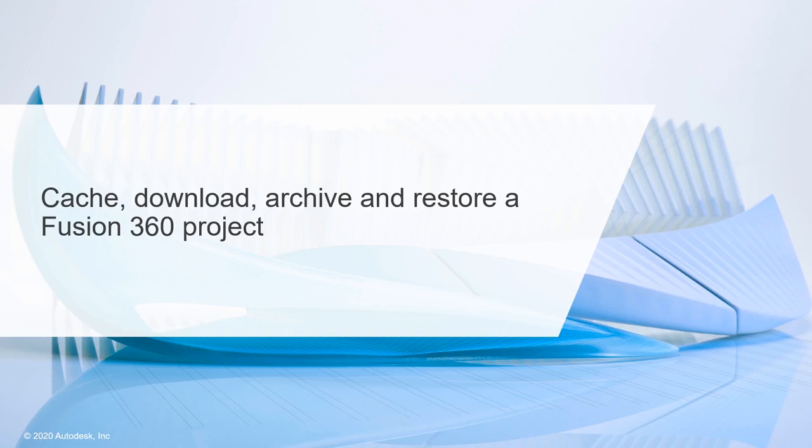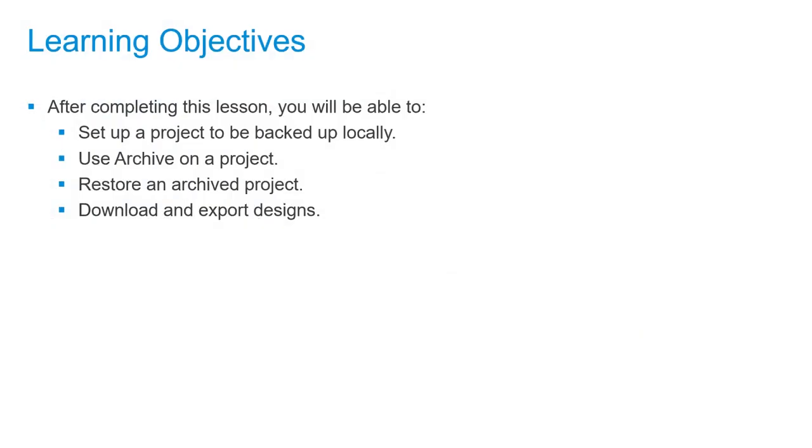In this lesson, we'll cache, download, archive, and restore a Fusion 360 project. After completing this lesson, you'll be able to set up a project to be backed up locally, use archive on a project, restore an archived project, and download and export a design.